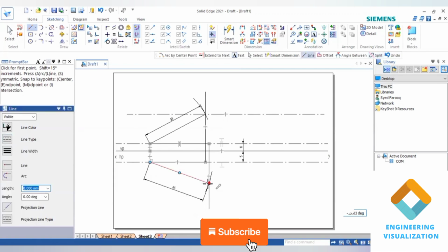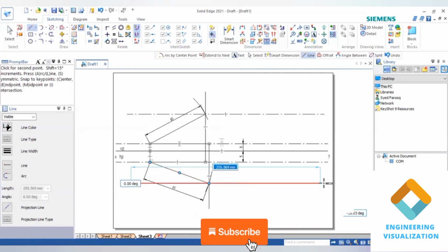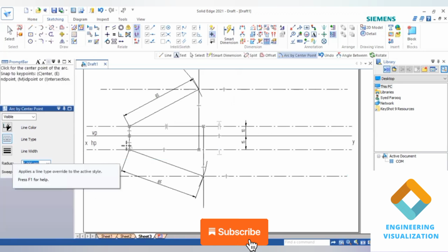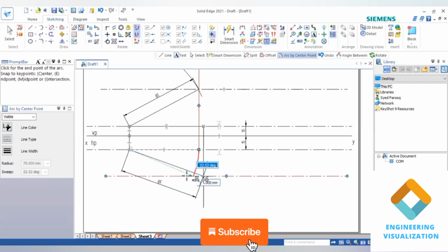So here at the bottom below the XY line also we have to draw another locus line. Now go to arc by center. By measuring this 75 and 80 mm upper end lengths, you have to draw an arc to draw the upper end lengths. First select the 75 mm length, cut an arc. Same way for 80 mm length, cut an arc.